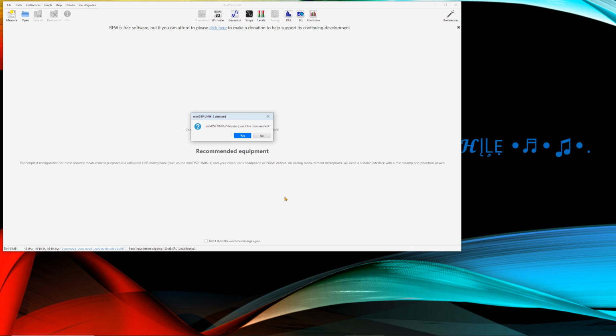For multiple measurements, try to keep microphone positions symmetrical around the central listening position so the averages make better sense, and take the central listening position measurement last so that you can keep the microphone there, as you will need to repeat many measurements at that point for speaker level, distance and crossover adjustments.